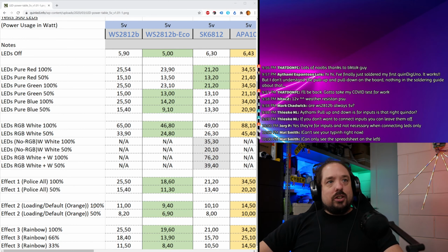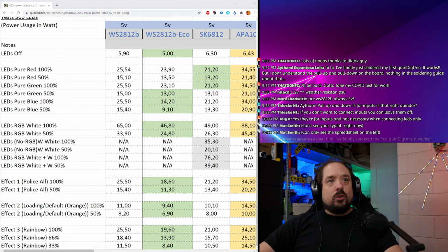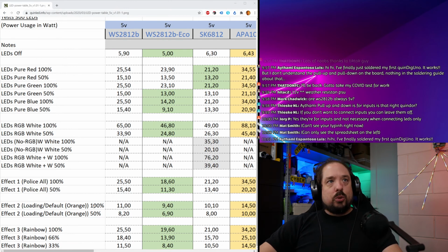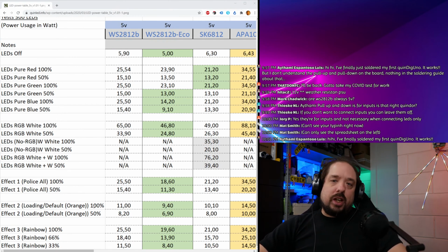So instead of saying, okay, we need half of 65 watts, we only need 1/3. That's 21.6 watts. And then let's see what that is in regards to, because I've tested all of this and I know what kind of works and what doesn't. Yeah, this is more the calculation I wanted to get to. That means we need 4.3 amps.